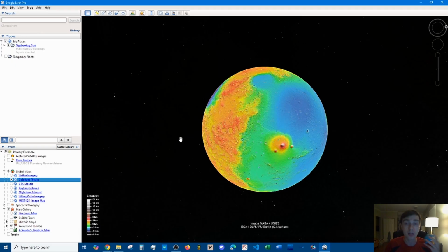The other question is, do I want to, instead of using the higher ISP and low boil off of hydrazine, compare it to a cold gas thruster? Cold gas thrusters are a whole different ballgame of propulsion. They offer a very terrible ISP.